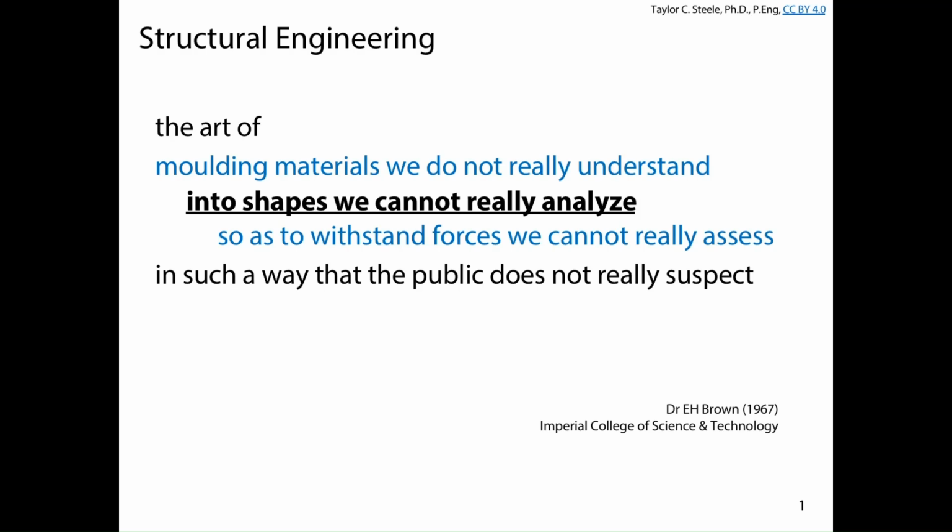And then in the lab the other day, we reminded ourselves how to do those statics problems so we could get shear and moment in arms, for example. And when we come to flexural members later on in the course, we'll use the shear and moment to figure out how big, like what W shape are we going to be using to work as that joist or as that girder. So we talked a bit about gravity framing.